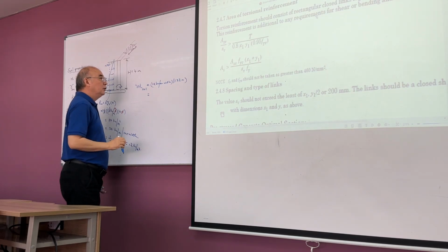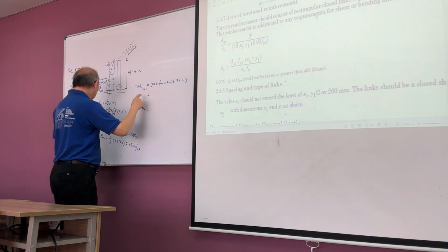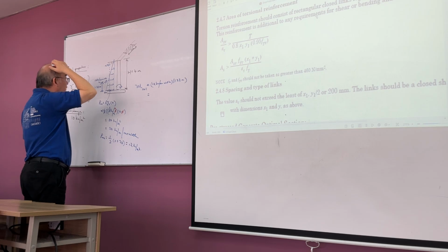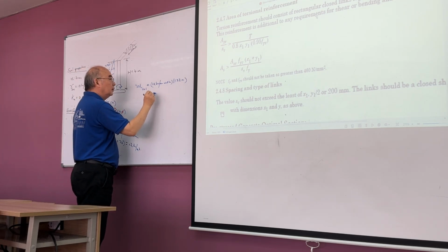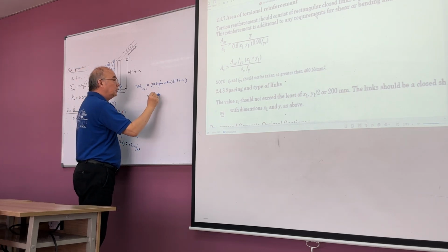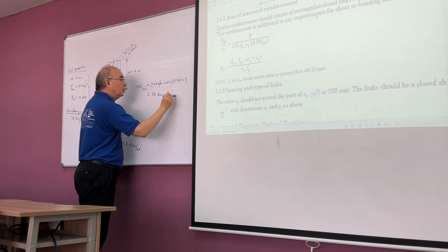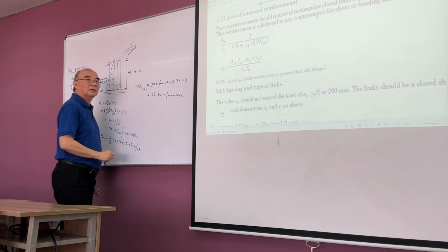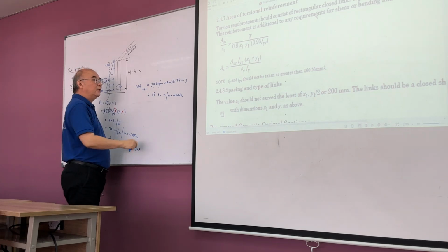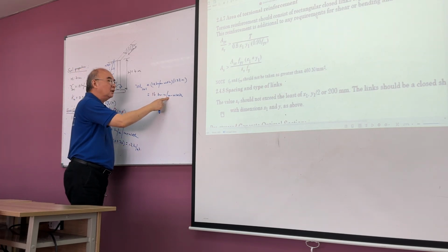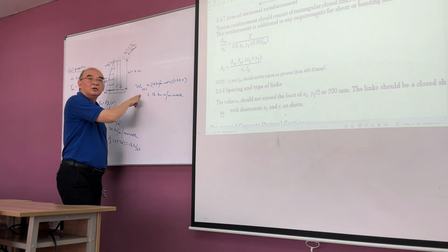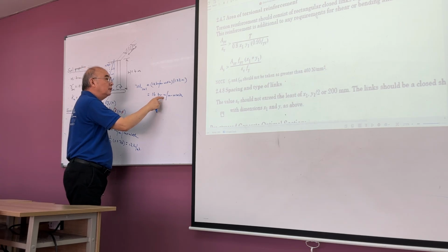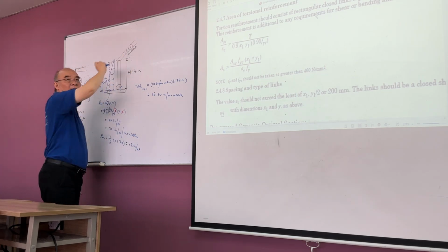So what are the units? This is 16, okay? Kilonewton meter per meter width. If you cancel this meter, it will be kilonewton. But kilonewton is a force, and we are calculating the soil moment. So actually it should be kilonewton meter per meter width. Okay?